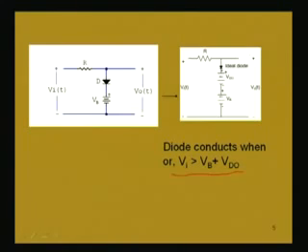Conventionally it is denoted like that, this potential is negative is a ground actually. So, V naught is equal to when the diode conducts. Now, this is an ideal diode, because normally we replace the diode by its ideal diode and battery Vd naught.